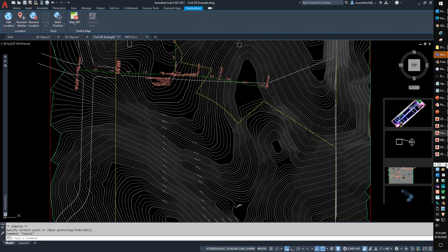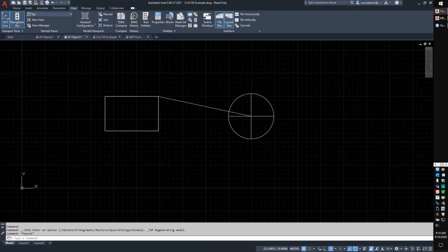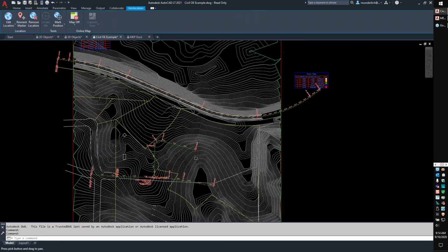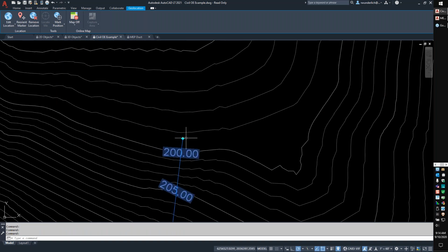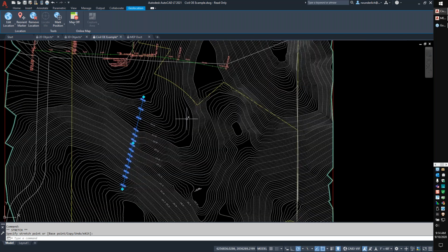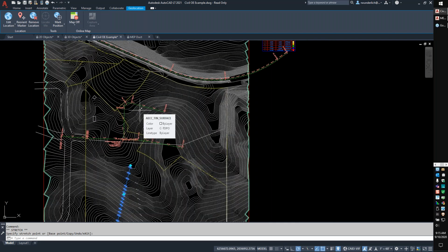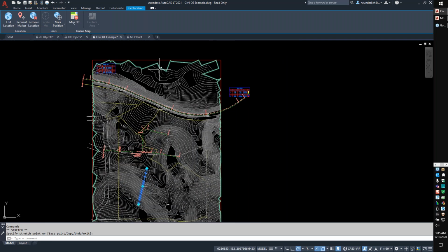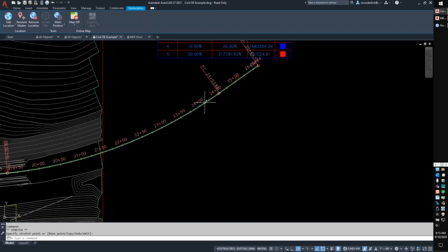I can actually come back into AutoCAD LT. So now I'm down in LT because again, no view cube, no visual styles up here. And you'll notice that with that object enabler, I can click on this and I can do the exact same thing inside of AutoCAD LT. So there are some objects I can manipulate and some I cannot inside of AutoCAD with the object enabler. So you can still see all of the functionality and still do everything that you are looking for in AutoCAD LT as far as being able to view the drawings, and you have the same editing capability.